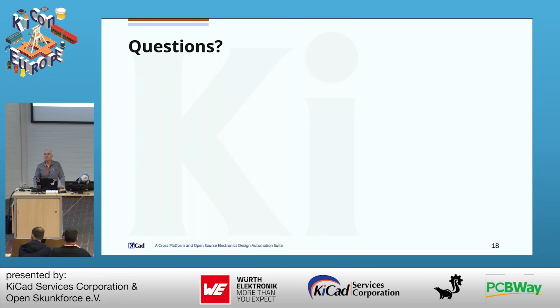I had a question about going back to the previous presentation about design rules. Does it also mean if you have the variants, that if there's different footprints, you can specify different design rules depending on the footprint? For example, as you mentioned, different powers or different size packages. So if you want to have more current, you would need a thicker trace on the PCB. Will it connect those things automatically, or will there be an option to, because it's the same net? Yeah, it's the same net, so it would be hard to do. Everything's done by net. Yeah, so that would be tricky. That might be a manual operation that you would just have to do.